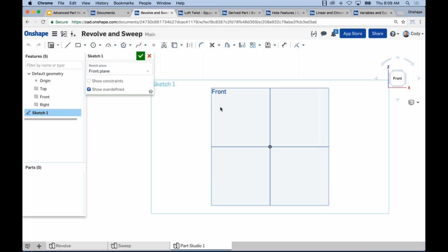And I would say the key thing when you're starting your revolve profile is just understanding what you want to rotate that revolve about, what we refer to as a revolve axis. And oftentimes that's where I'll start. It's not a rule, it's just a best practice, at least to identify, if not create, what that rotation axis is. And so that's where I'm going to start.